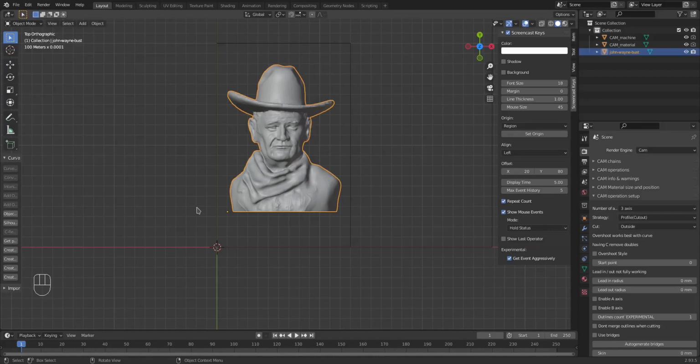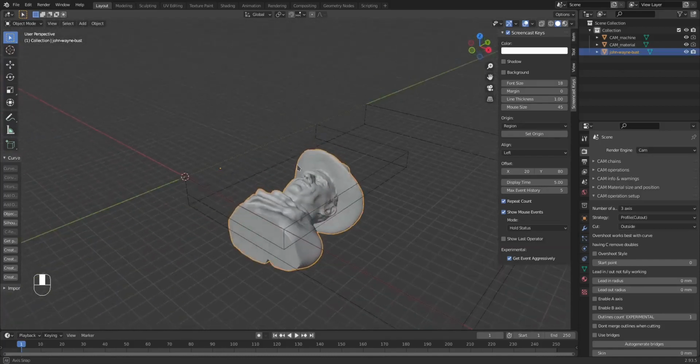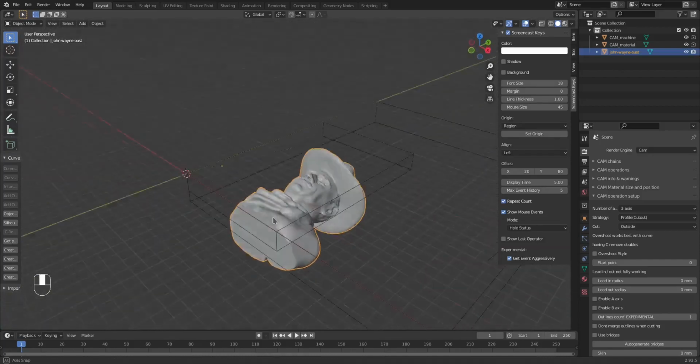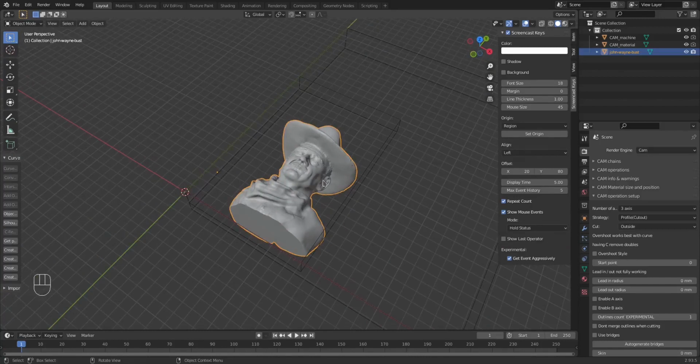It'll just be cutting that out. I will leave these little bridges, little tabs, as it's called in some software, to keep the model from breaking free from the rest of the material. Just little bitty sections that aren't cut out that I'll have to manually cut out once the CNC machine's done its work. And I'll have a roughing operation.